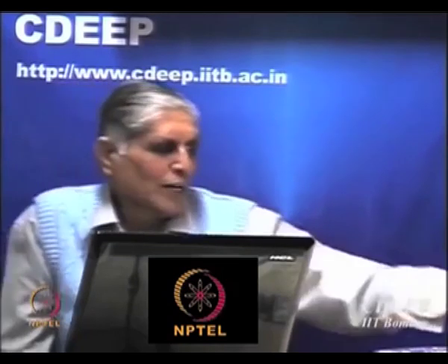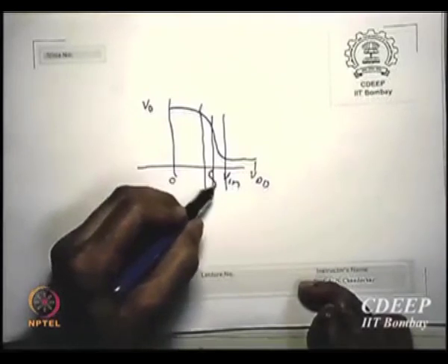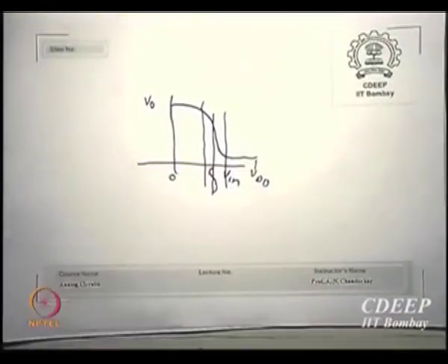Okay. And that is why if you bias your circuit only in this range, let's say this is my biasing voltage, then I can apply an input signal over it which still keeps output such that V0 Vin is in linear mode. Okay. That is where the analog differs from digital.